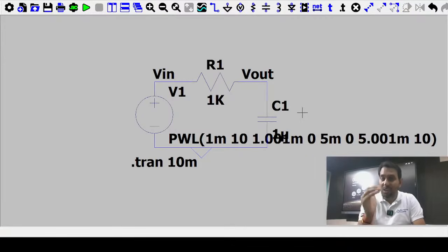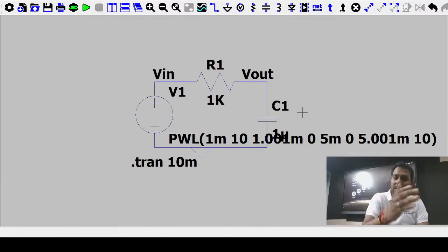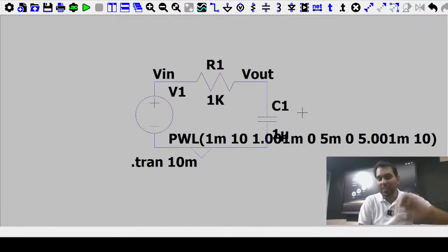These are the ideas you can understand, and whenever you have a CMOS inverter, a cascade structure, a differential pair, an op amp, or anything MOSFET related, these are the very important points where we will discuss. What is happening here? This is similar to an RC circuit. Everything is related to the network and RC, so if you are good in this understanding, you can go further.